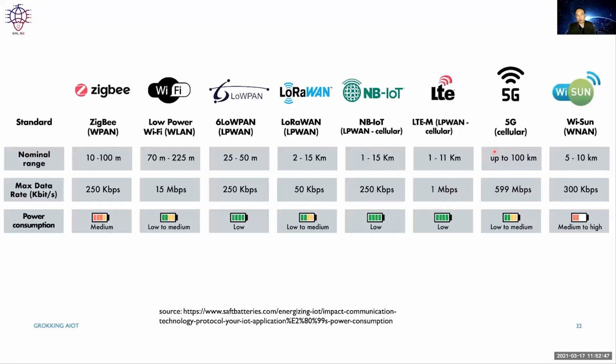The other challenge, of course, for these different radio technologies is that the density is different. How many devices you can squeeze per square area is quite different. Things like Bluetooth are not intended for very dense deployment, right? The Bluetooth network can only support a limited number of devices within a square area, whereas things like Zigbee and even NB-IoT can support a much higher density. So what's not present in this diagram, which is just comparing power, data rate, and nominal range, is also the device density, which is the fourth dimension, right?